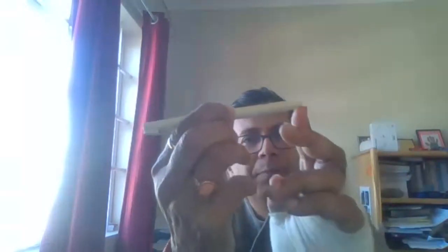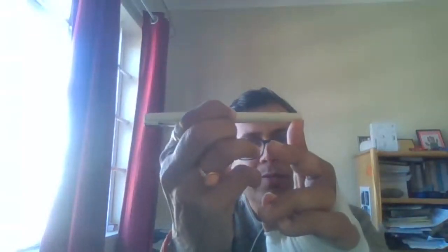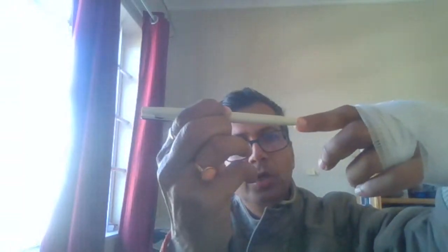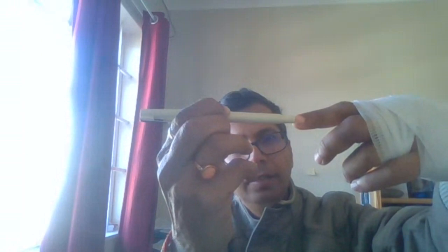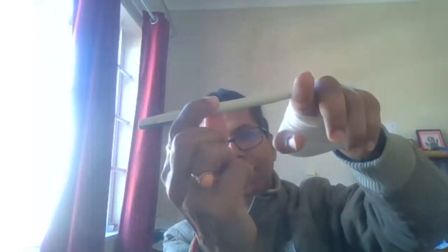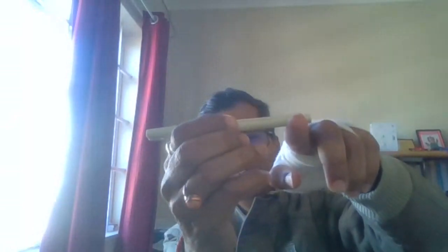So if you see this, if I push like this, this is your vertical force. If I push like this, this is a horizontal force, right? While you are finding the bending moment of this beam, your axis is like this. You are trying to rotate your beam along this axis, the axis which I'm pointing, right? You got me? That is your Z axis. You are trying to rotate everything along this Z axis to get your bending moment diagram. So that is Mz. Are you able to understand?